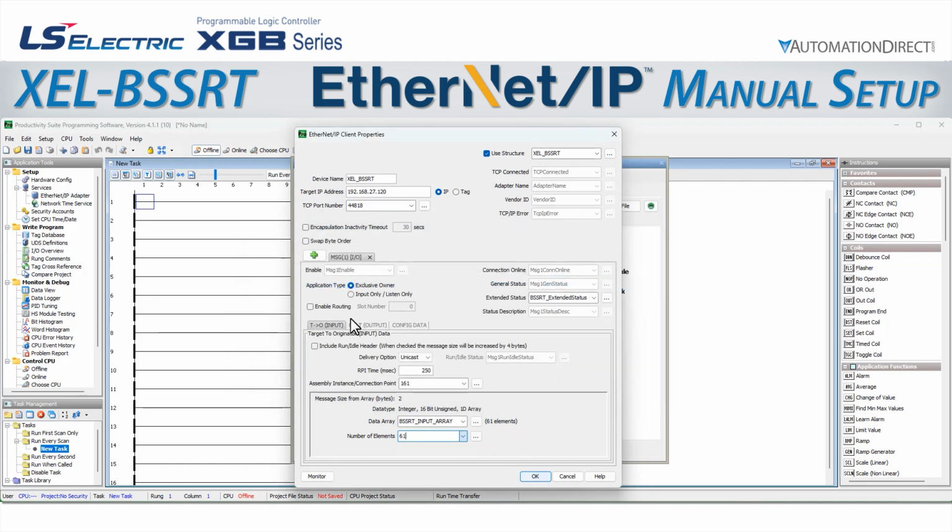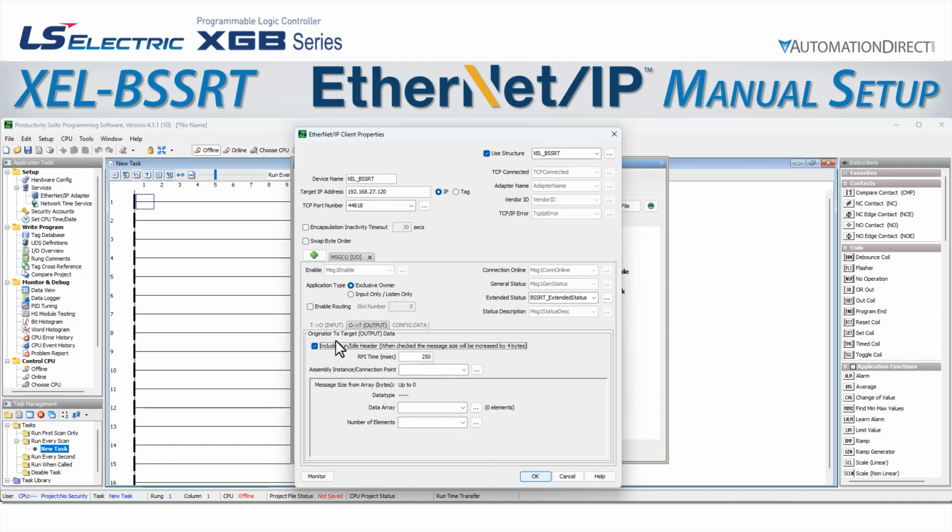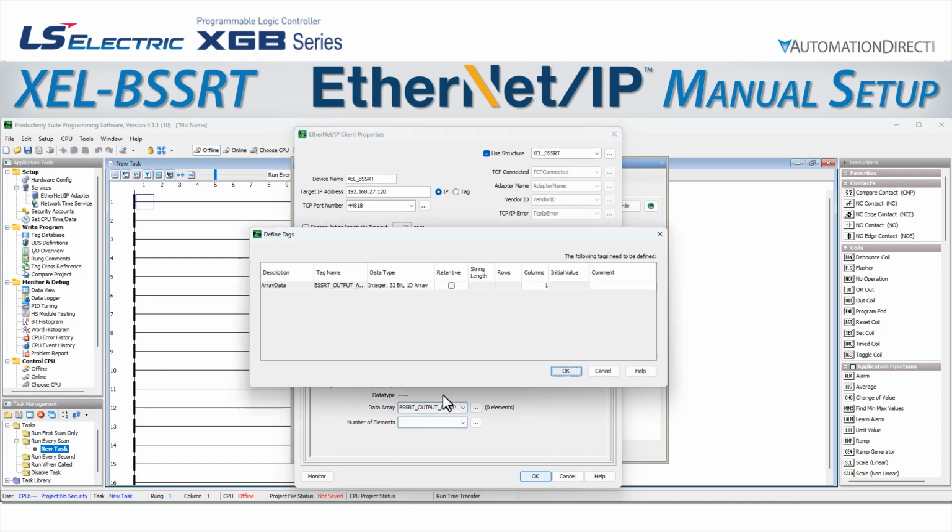Let's run the same setup on our output tab. This time we will keep the run idle header, as the help file tells us that our adapter expects that, and we will keep the 250 millisecond RPI and use the assembly instance of 162. We will name our array BSSRT Output Array, and we will create a 1D array of 16-bit elements and 8 columns.